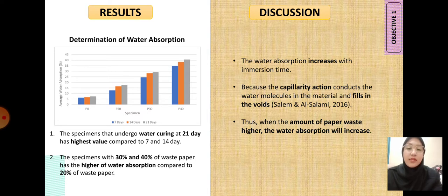The water absorption increases with the immersion time because the capillary action conducts the water molecules into the material and fills in the voids. Thus, when the amount of paper waste is higher, the water absorption will increase.